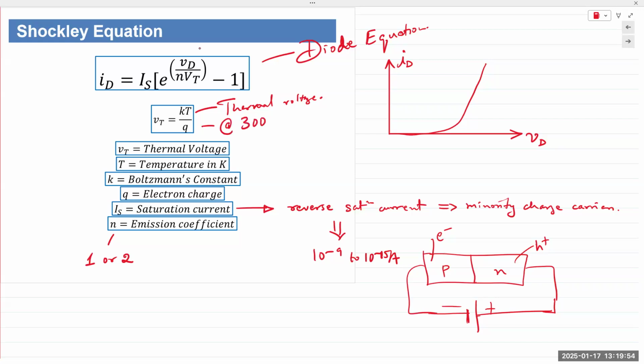At 300 Kelvin, just typically room temperature, the value can be calculated as 25.8 millivolts. Depending on the author, you might also see 25.9. But again, you can calculate this easily. If you take Boltzmann's constant in the units of electron volts, which is 8.6 times 10 raised to minus 5, you simply multiply it with the temperature, and you can calculate the thermal voltage at any given temperature.